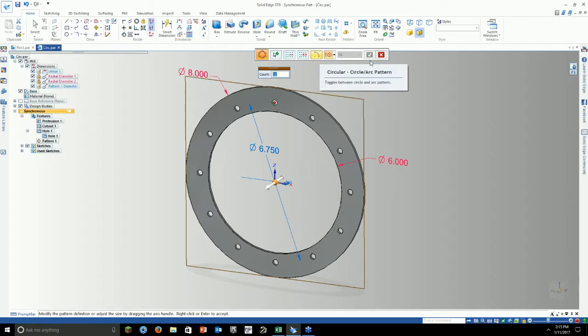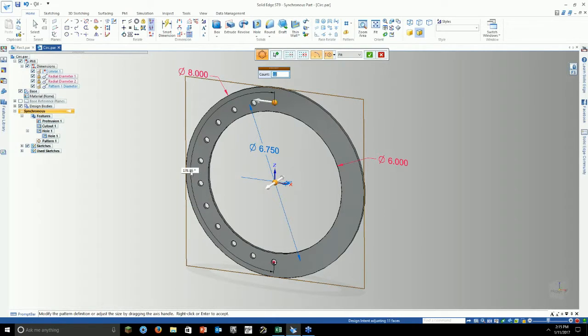And we do have another option here. Again, we have the fit and fill option. In this one, we can also just do a partial pattern. By just dragging the geometry around, you can reposition it, or we have the actual dimension handle. If I want to make this 180, and if I want to make this only 6 holes now, so I only have 6 holes along the pattern, you click the arrow to change whichever side you want that pattern to go to. Again, you have the suppression options by suppressing individual items and or by suppressing via a region.